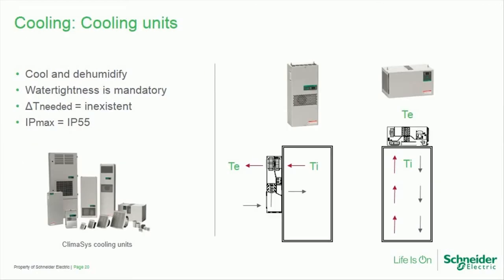Cooling units. They permit the components installed in the enclosure to be at the temperature needed to operate properly, regardless of the outside temperature. Without the air inside coming into contact with the outside air, dehumidifying the enclosure, they reduce the relative humidity and water in suspension inside the enclosure as far as possible.